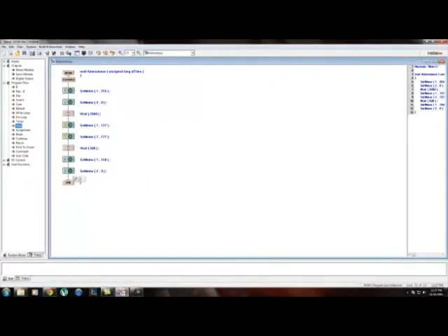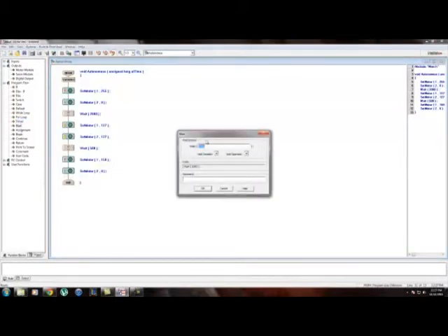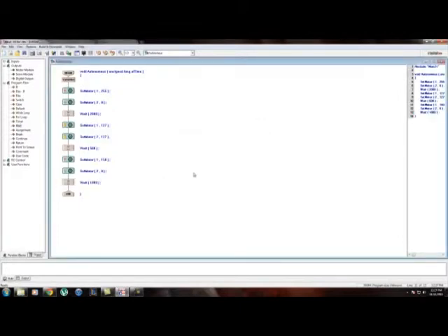But again, let's do a wait time, so it actually works for more than a millisecond. And let's go for a full second. But remember, you're going to have to play with this autonomous. We at Team 1138 play with this for hours and hours on end, and still need to tweak it a lot. So this whole autonomous will basically drive forward for 2 seconds, stop for half a second, and do a gentle turn for a second.